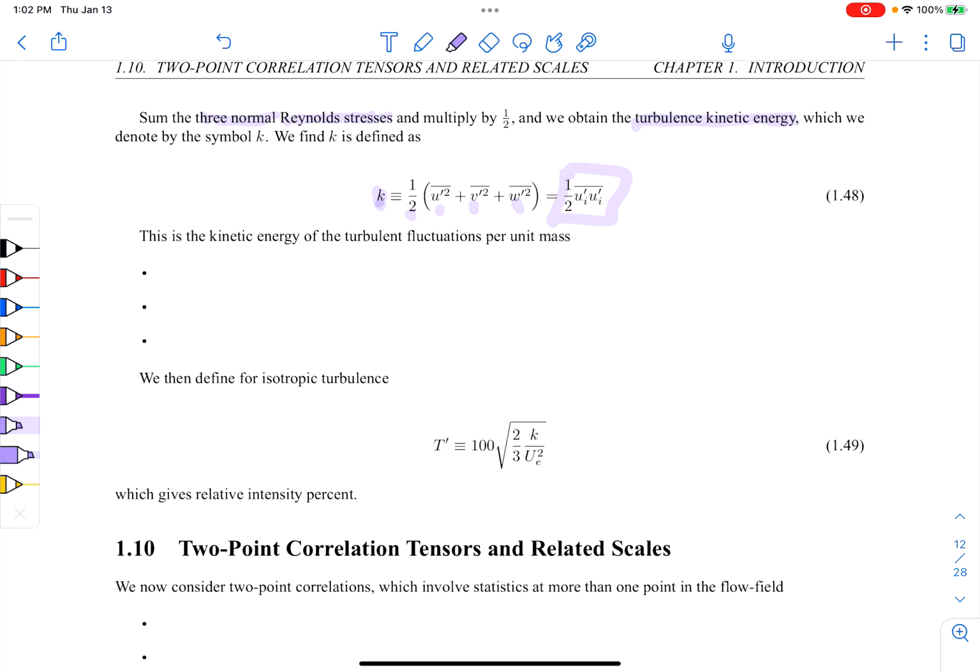Another great thing about trying to predict K is something that's usually we can try and approximate and measure with experimental techniques. So it's a wonderful quantity because we can directly try and compare K from a CFD code to an experiment and validate our model. Because if we can't predict K and know how much the energy of the turbulence at different spatial positions in the flow is, then the model's not very good. It's not predictive.